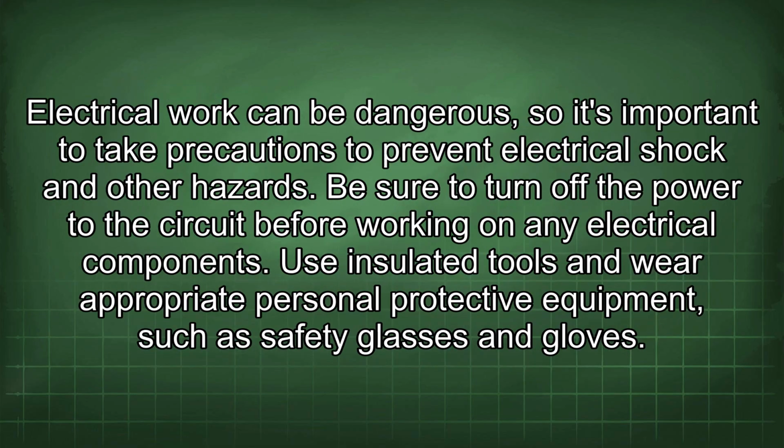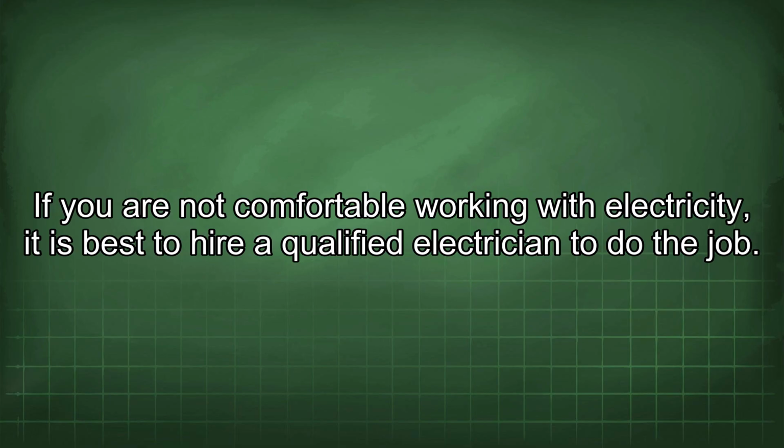Electrical work can be dangerous, so it's important to take precautions to prevent electrical shock and other hazards. Be sure to turn off the power to the circuit before working on any electrical components. Use insulated tools and wear appropriate personal protective equipment, such as safety glasses and gloves. If you are not comfortable working with electricity, it is best to hire a qualified electrician to do the job.